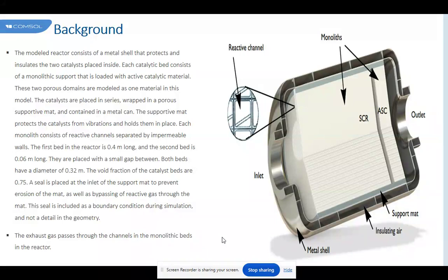The relationship between the variables is slightly nonlinear. It is somehow striking that the two cases with the evenly distributed flow areas led to an almost identical pressure drop regardless of the placement of the monolith with the highest and lowest cell density, core or ring. This result was not reproduced when analyzing the sensitivity of CO conversion, where both trend lines, 400 per 6.5 and 900 per 2.5 in the core, behave differently, as shown in this simulation.